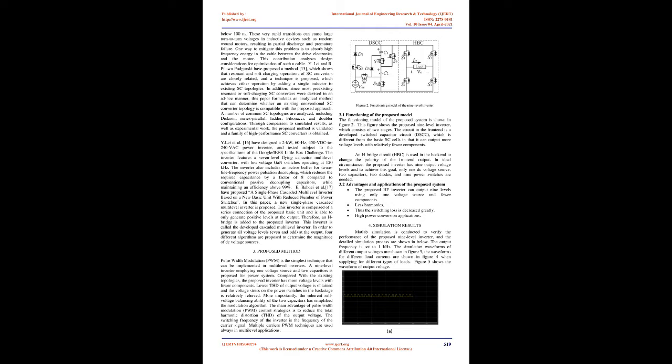High step-up DC to DC converters deliver high voltage DC output which is required for DC power systems such as photovoltaic grid-connected power systems, very big windmill farms, power generators used for medical electronics used in hospitals such as X-ray, satellite ion thrusters, and pulse electric field, PEF, related applications. In these applications, high step-up converters are usually required to generate DC voltage at kilovolt levels from sources at hundreds of volts, with rated power ranging from hundreds of watts to few kilowatts.